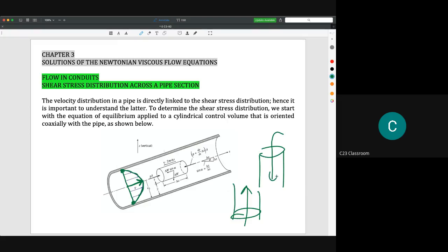And then we might be discussing a pipe from a tank going to another place like this. The main difference is that in Poiseuille flow, pressure exists inside the pipe. In Couette flow, not always but almost, we take atmospheric pressure acting on the flow, so we can simplify the equation more compared to Poiseuille flow.